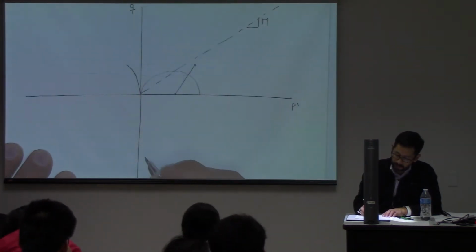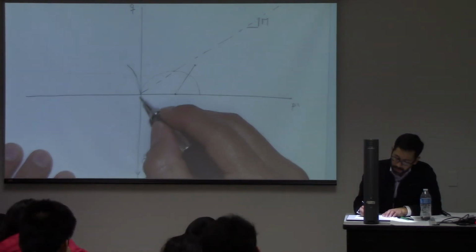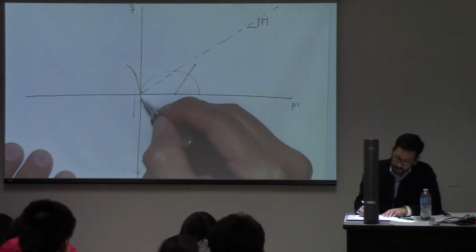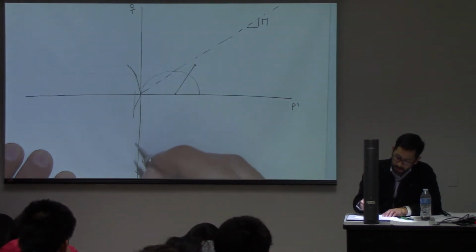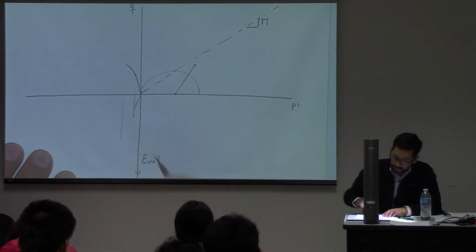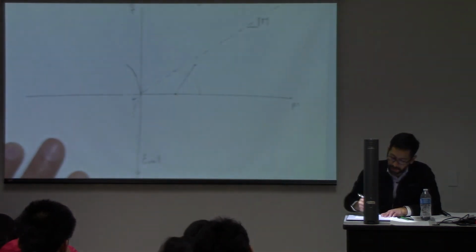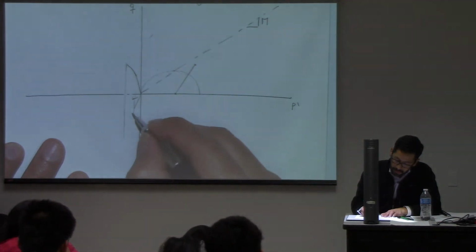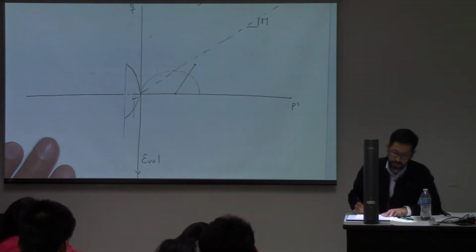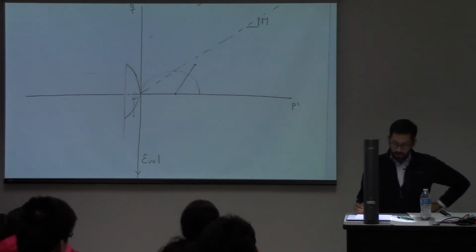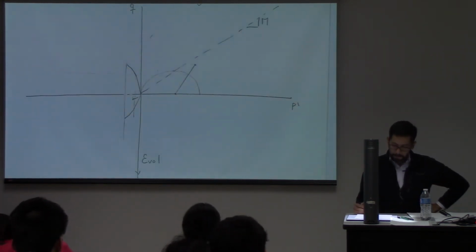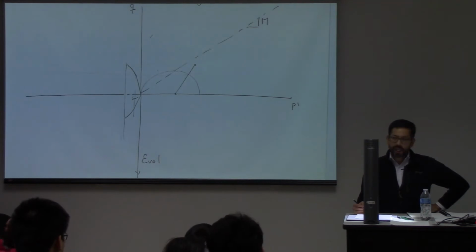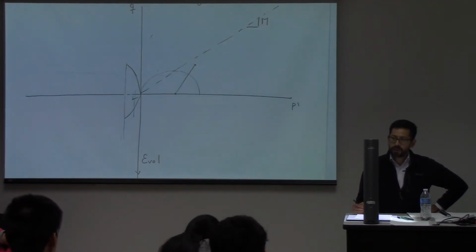And if I were to plot here volumetric strain, this one will be up to this point elastic, and when I get to that point I already have plastic strains, and this will bend a little bit like this. Okay. Do we agree so far about what has happened?